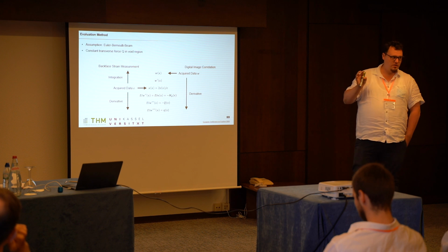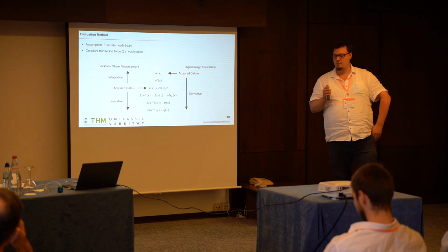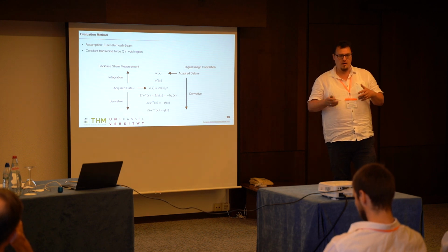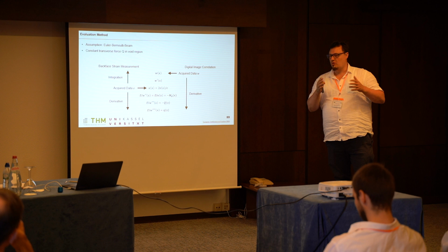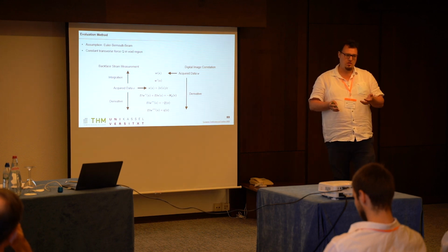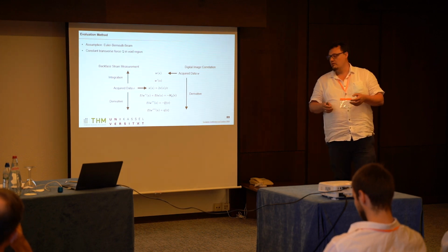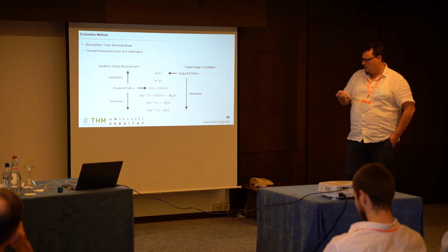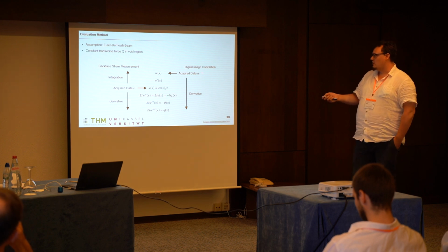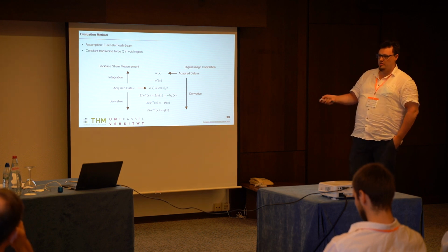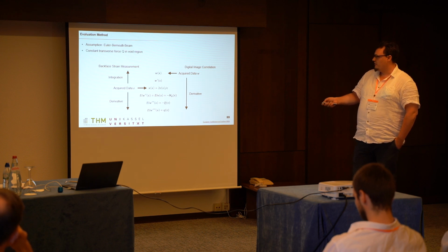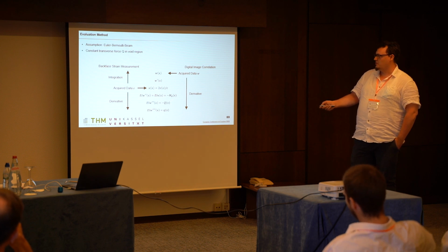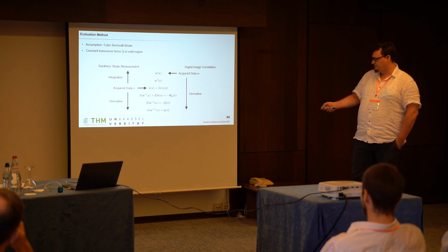Now the evaluation method. We assume for the adherend that we have Euler-Bernoulli beam theory, and we expect at the void's position a constant transverse force, or the third derivative of the deflection curve is constant. For the digital image correlation, our acquired data is the deflection curve w(x). We have to differentiate three times to get the third derivative, or the transverse force.